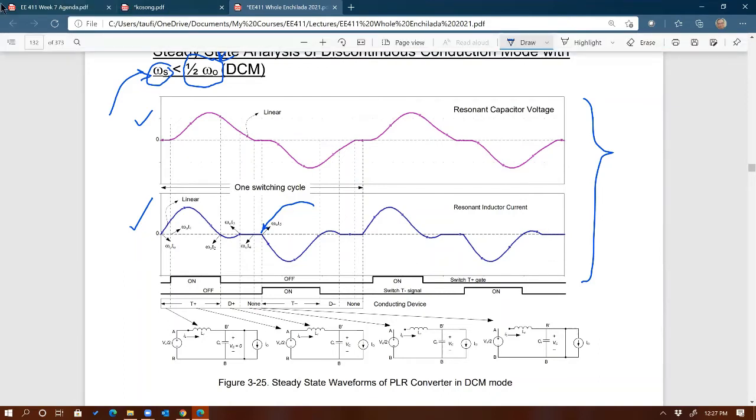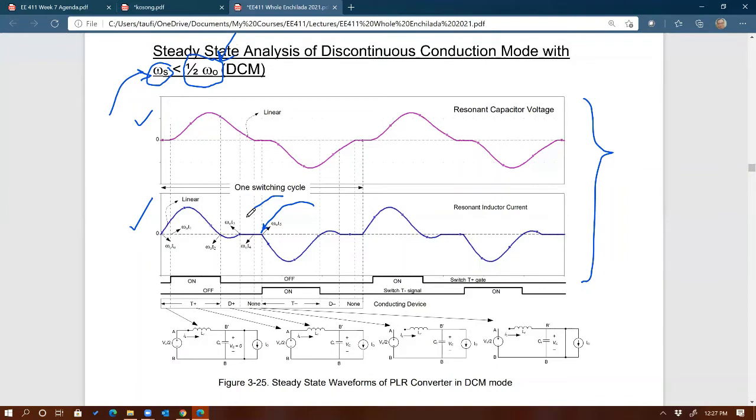And you can see that there is a limit on how high a switching frequency you can choose. Imagine if you keep shifting this point to the left instead of to the right. To the right, there is no limit, but to the left, you can only shift it all the way down to that point right there. And that's called boundary conduction mode.